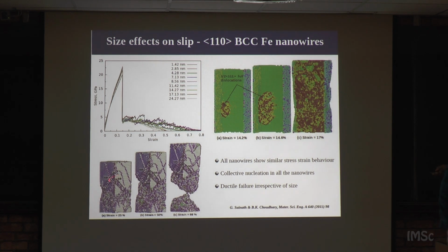First an elastic increase, then a drastic drop due to defect nucleation, and then fluctuations until failure. Since it is a dislocation dominated deformation, you observe various kinds of features like slip bands, dislocations, slip steps, all sorts of things. So, basically not much influence of size is observed in this orientation.